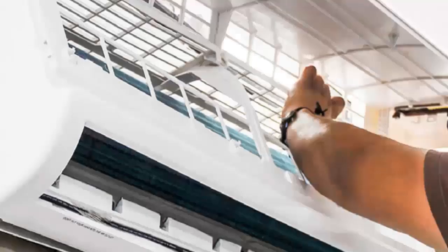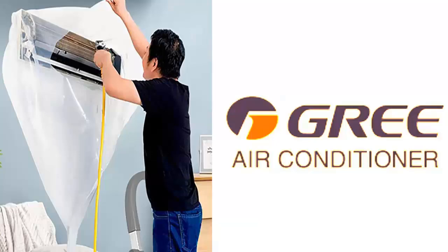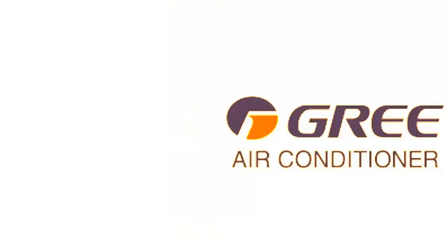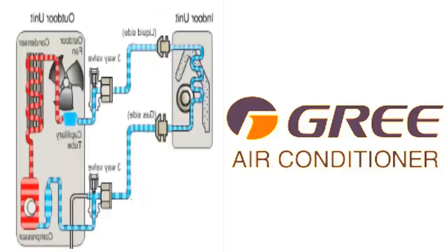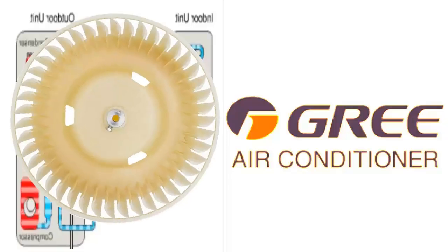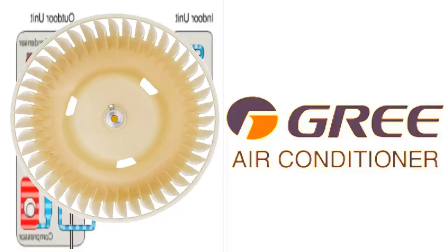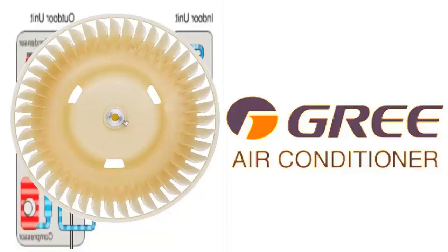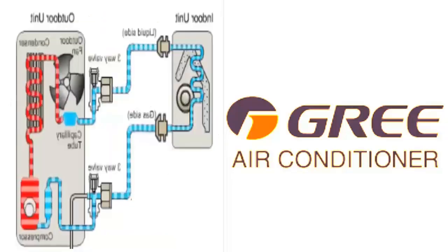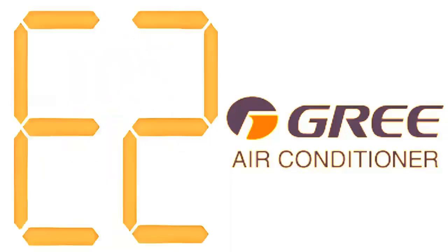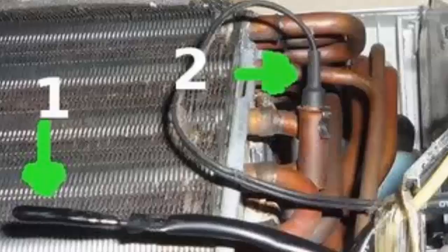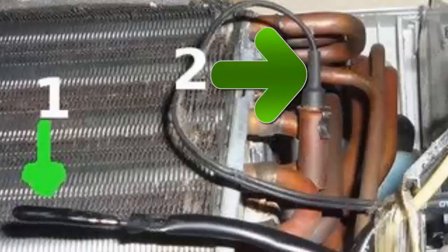A. Check and clean the air filters, ensuring there are no obstructions in the air inlets and outlets of the indoor unit. B. Additionally, check the proper rotation of the indoor unit fan. If rotation issues are detected, focus on resolving this part. C. Finally, test the temperature sensor using the procedure explained at the end of the video.